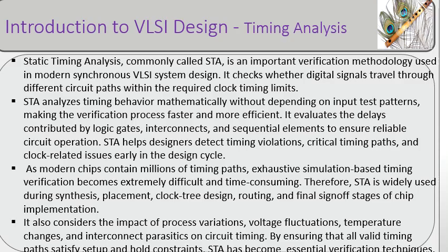STA helps designers detect timing violations, critical timing paths, and clock-related issues early in the design cycle. As modern chips contain millions of timing paths, exhaustive simulation-based timing verification becomes extremely difficult and time-consuming. Therefore, STA is widely used during synthesis, placement, clock tree design, routing, and final sign-off stages of chip implementation.